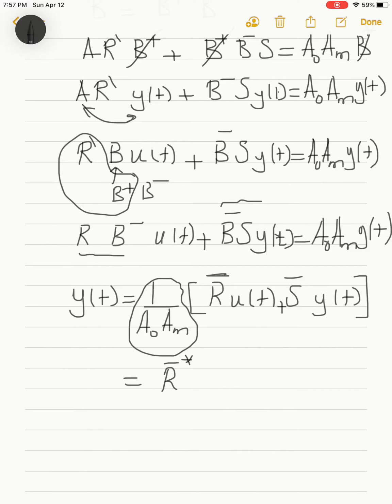I'm doing the star here to remind ourselves that this is in the backward shift operator, and I will get the filtered signal. Normally this would be minus d naught, and d naught here is the delay in the system. As I mentioned before, the delay would be the difference between the degree of the denominator and the numerator of the plant. And here I will have S bar star times again the filtered signal.